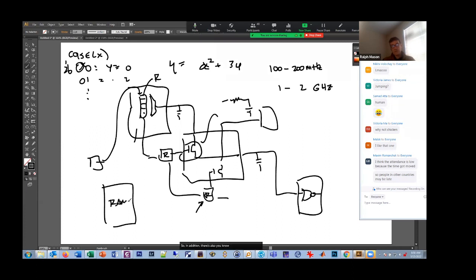let's call it a RAM block. There's also RAM blocks that you can route into these switches as well, and they can be programmed from the pin as well. And this could be like 1K of RAM or something, or even bigger blocks. So you can load those in with the bit file. So you have memories, you have logic, and you have routing switches.